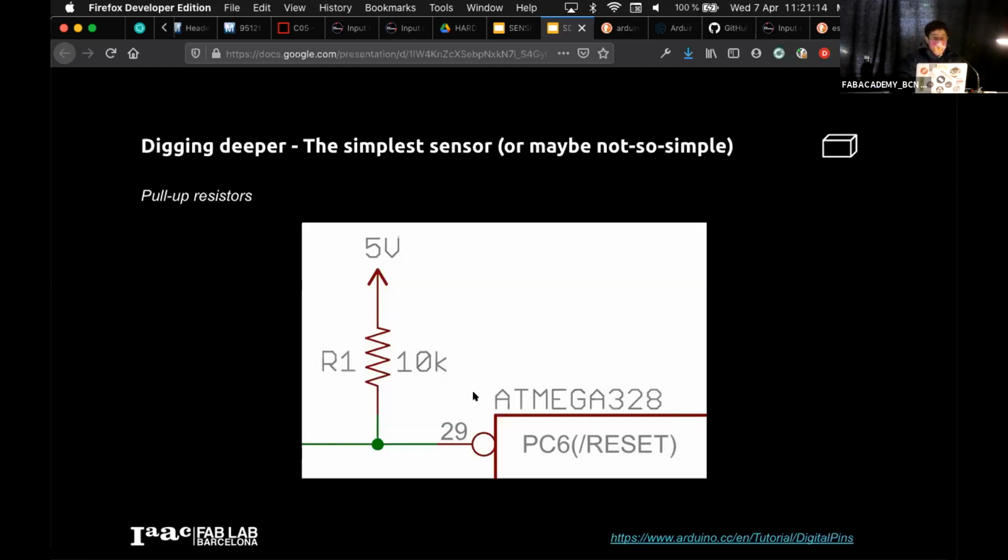In this case, I assume that this pull-up resistor is on the pin on the left. If there's a switch here, there's our switch, and then I have ground here. Because if I didn't have ground and this was VCC, when I press the button, I have VCC. And when I don't press it, I also have VCC. So I have 2 possibilities and I only have 1 option. So I'm not able to discern, right?